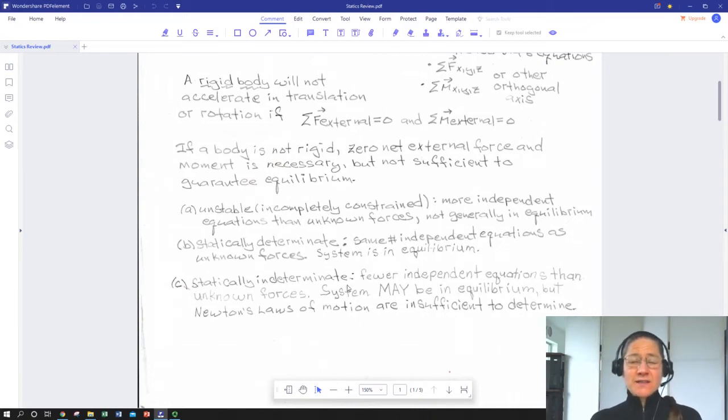In a lot of cases, this state of over-constraint can cause bad things to happen with respect to fracture. We'll have that kind of situation approaching what we'll later learn is called plane strain conditions, where it's hard for things to yield. So that would be a mechanics of materials and material science idea of an over-constrained system.